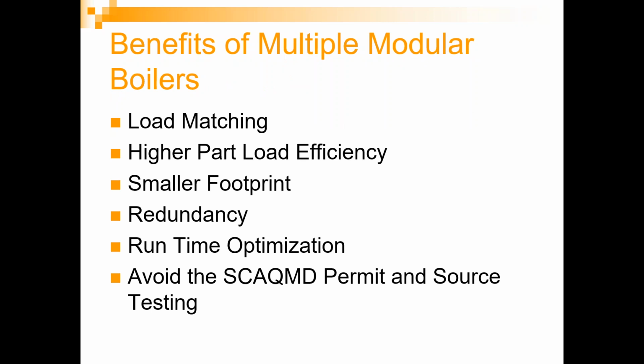So then we start to consider the benefits of multiple modular boilers. If we look at multiple modulating boilers, we can look at better load matching, higher part load efficiency. Typically, a lot of these modular boilers have smaller footprint, built-in redundancy. We can get runtime optimization.